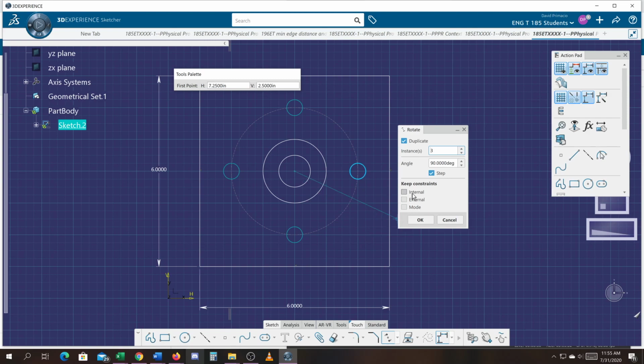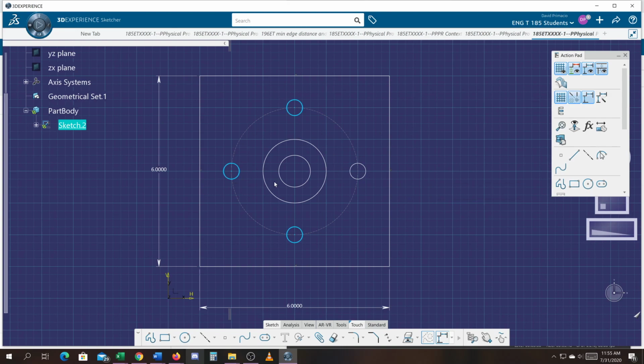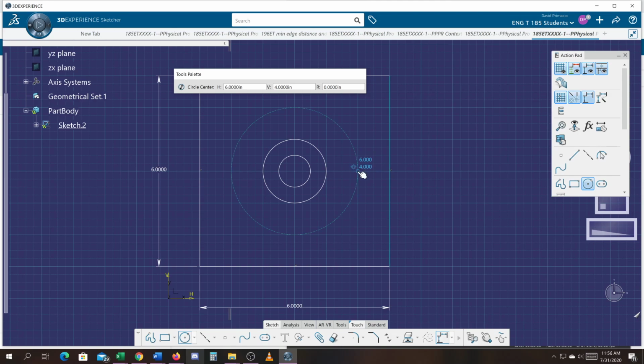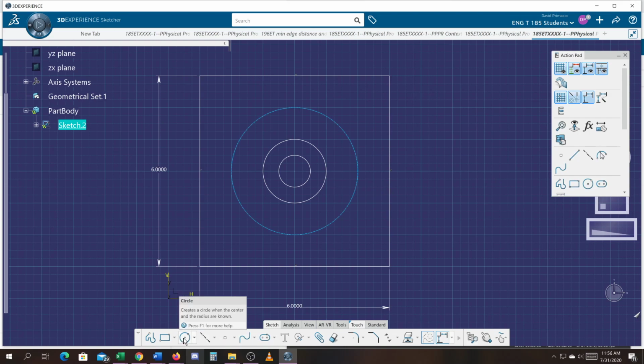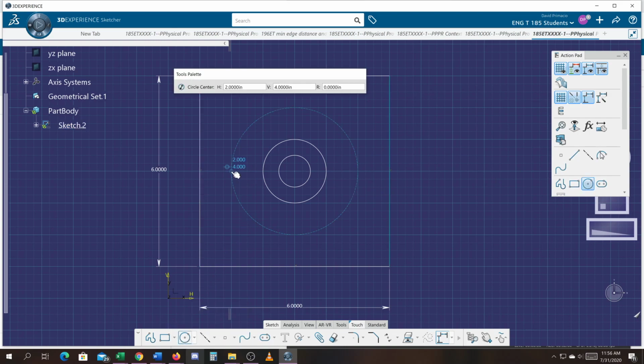Now, the internal external links is supposed to keep that linked up. Okay, so if I don't have them turned on, I say okay, it won't follow through with any constraints. So I'm going to undo that, and I'm going to recreate that circle. And this time I'm going to make sure I got that coincident on. Now, watch out because that blue line on the vertical is trying to link up to it. I'm going to try and slide it around so I'm not. Oh, I don't trust that. Undo. Try and create another circle. I'll start here. Okay, get that one there.